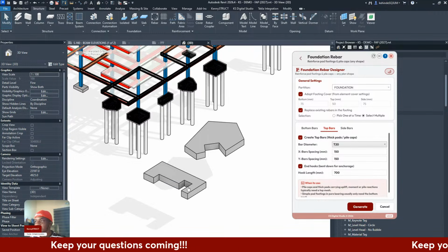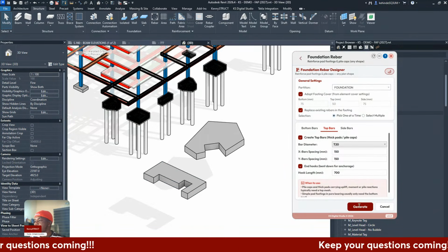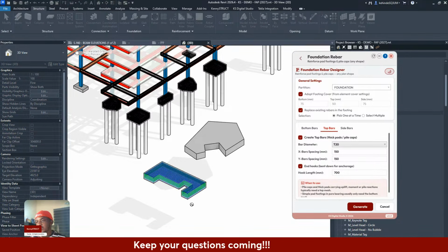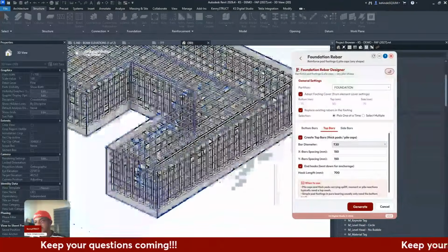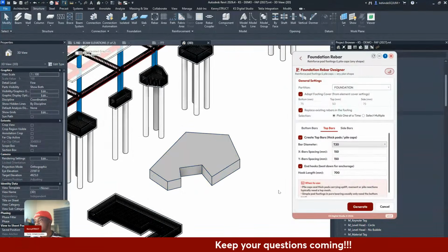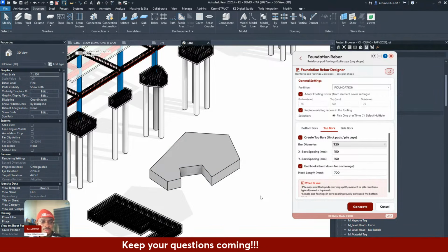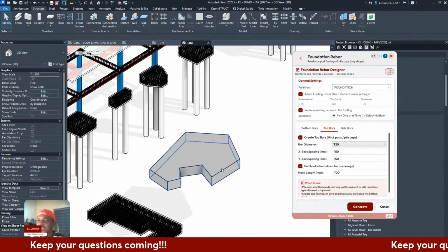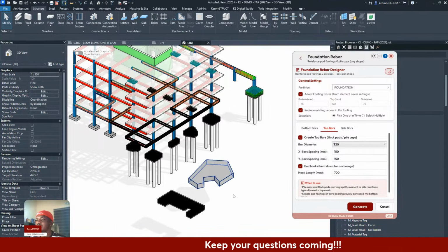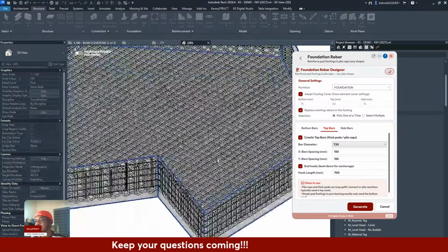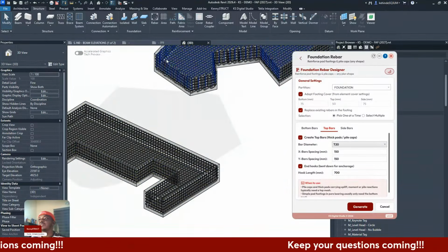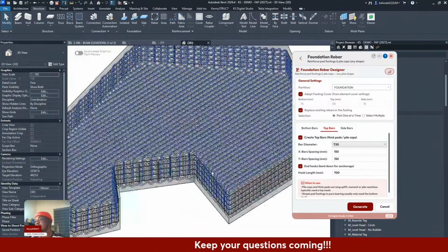Let's generate and click. I like to use it one at a time. Poof! Amazing. Does it amazingly well. Same thing as this. I removed. Yep. So you can see it. There you can use the split rebar to split bars that are more than 12 meters or something.